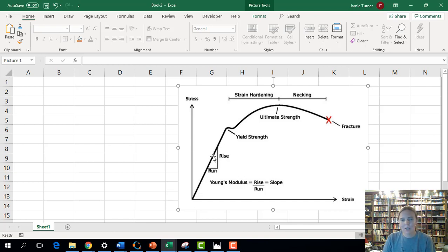So this is a characteristic. A lot of metals follow this behavior. So if you have something brittle, you would have a very steep slope with not too much plastic deformation. It would just suddenly shatter into 1,000 pieces. Versus if you have a ductile elastic material, then it would just take a little bit of force to really stretch it out.